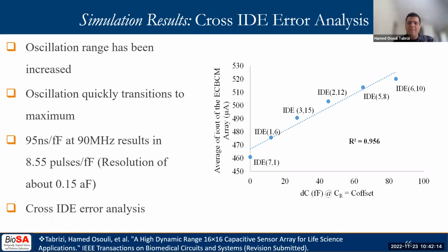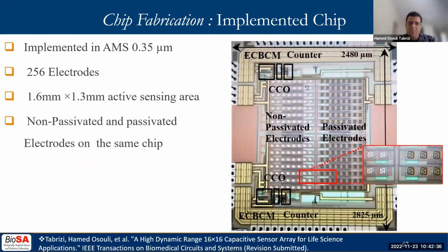Different amounts of capacitance have been applied to them, and the average of the output has been calculated and plotted. The curve shows an insignificant amount of deviation among the pixels. That is an indicator of the uniformity of the multiplexing structure without analog switches among different pixels.